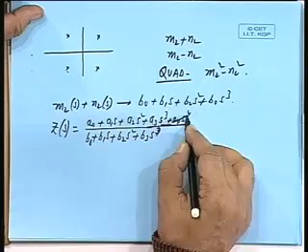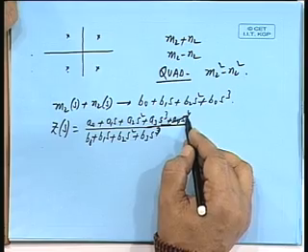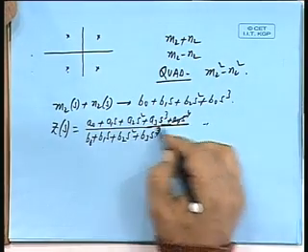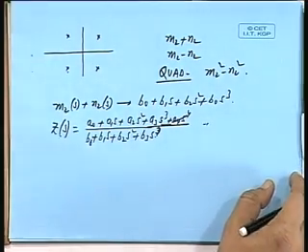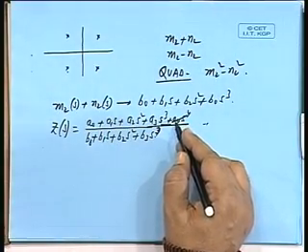Any additional x will also give me the same real part. The real part remains unchanged if you keep on adding reactances. So we will consider only that reactance function which is just required to realize Z(s). We will not go further beyond this. s to the power 4 by s to the power 3 will give me by division one free s term, something like a free inductor, and that can have any coefficient a4, a5, a6, it can have anything.